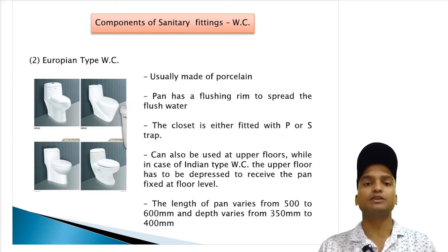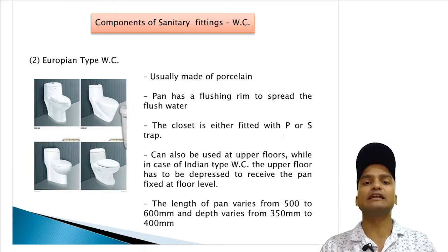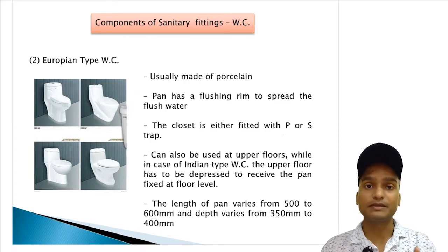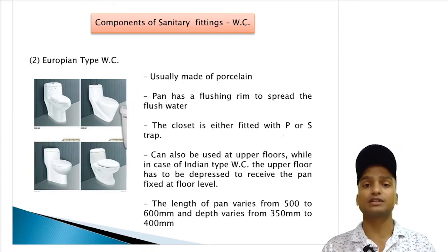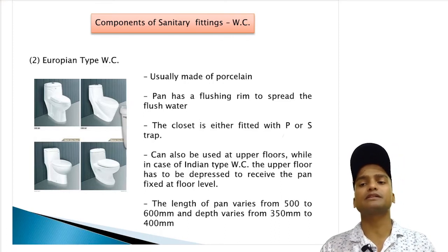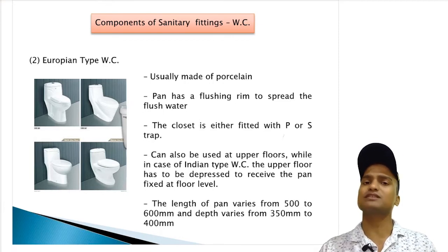And which type of clay do we use? The clays are also of different types, and we mostly include clay in the form of kaolinite. And porcelain can be of two types. One is hard paste porcelain, which is heated up to 1400 degrees Celsius, and the other is soft paste porcelain, which is fired at only 1200 degrees Celsius. In our day-to-day language, it is also known as chini mitti.